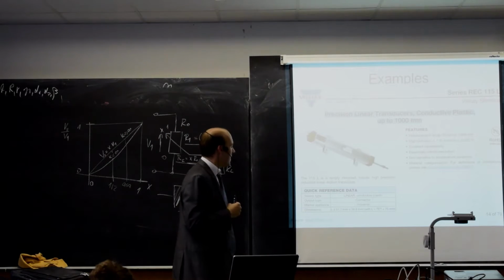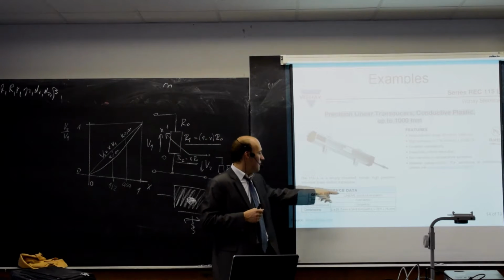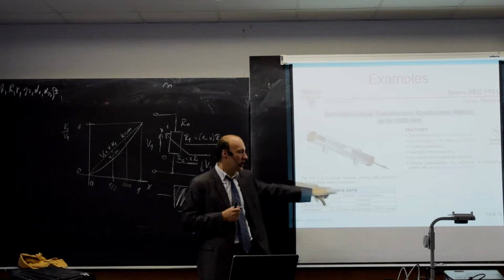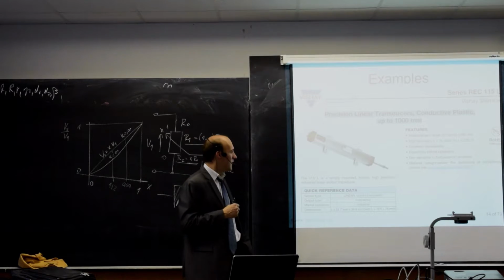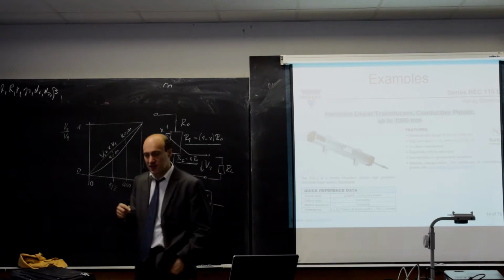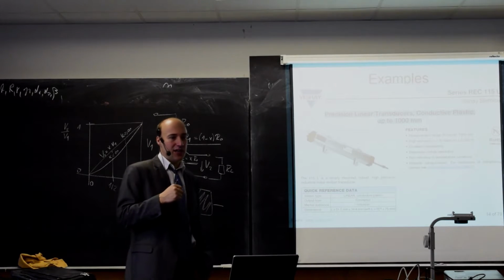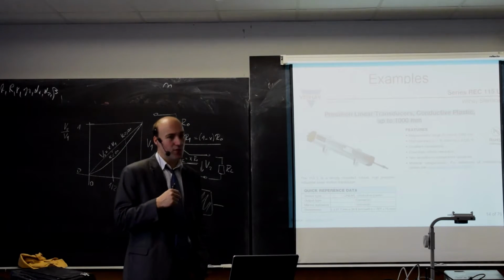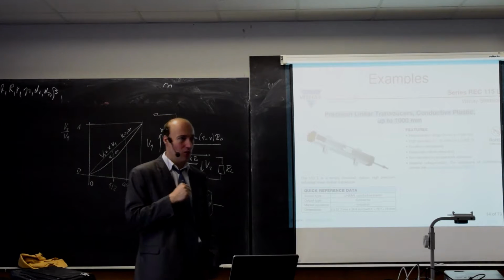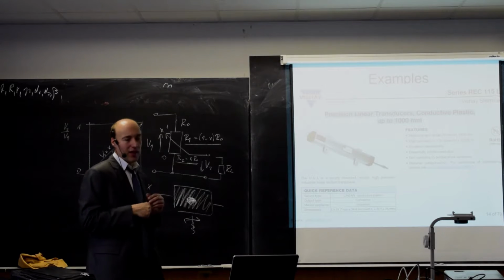It can be also more accurate. You see here sensor type linear conductive plastic. So conductive plastic is inside of this material. They say essentially infinite resolution. Yes, the layer itself has an infinite resolution, but then it always depends on the resolution of your measurement instrument. So here you are not limited by the sensor, but you are limited by the accuracy of the voltmeter that you use. If you use a less accurate voltmeter, you'll have a less accurate reading.